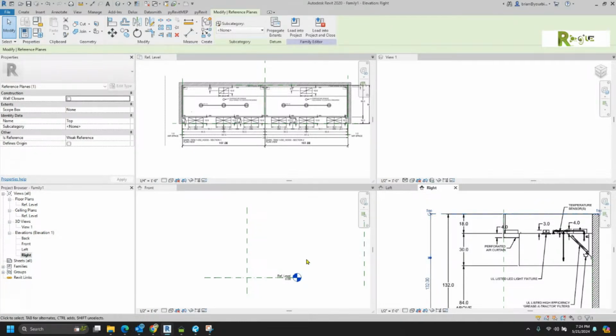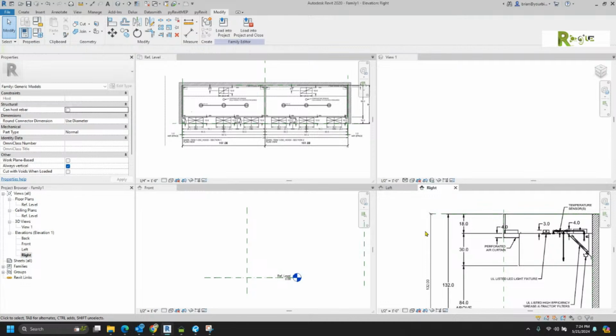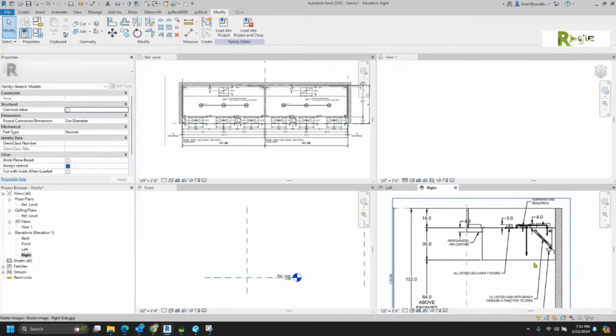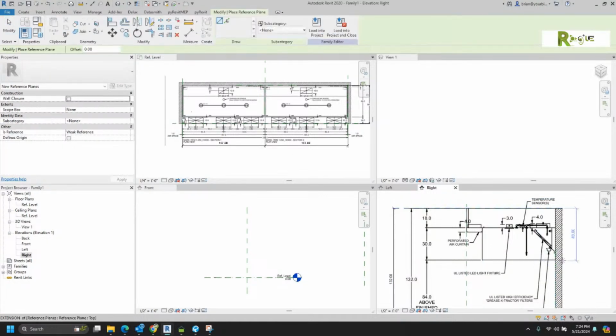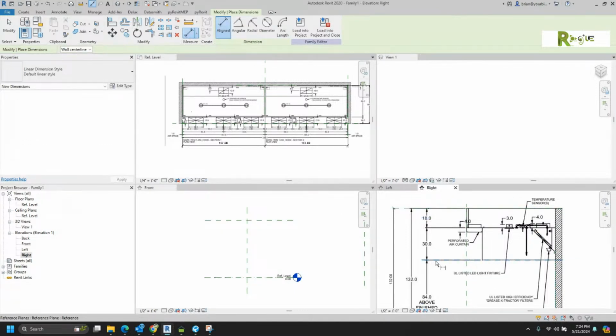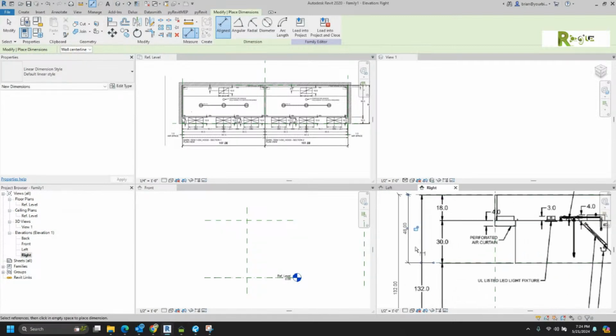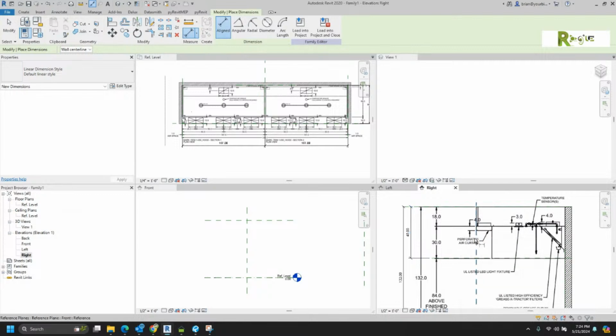And the reason, Ginger, that we put all of these reference planes in is it sort of is like the bones that the next thing, the object we extrude, will sort of stick to. So you really could put one down here at the bottom. And I think I'm going to. So if we put a reference plane right there, we would know this should be equal to 30 plus 18, 48. And it looked like that landed in the right spot.